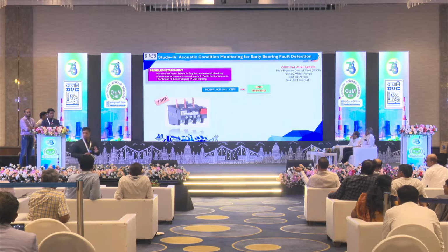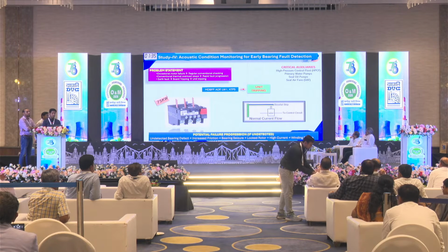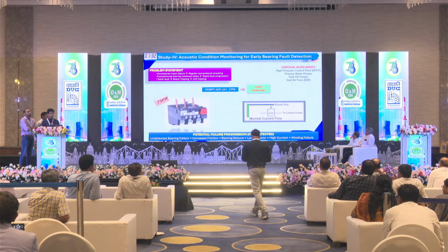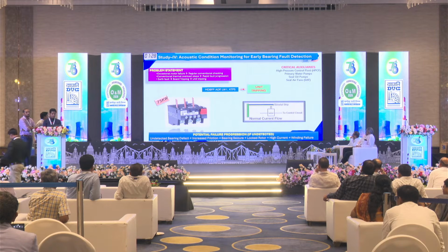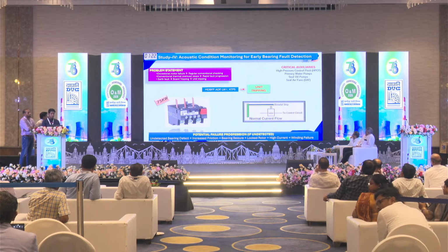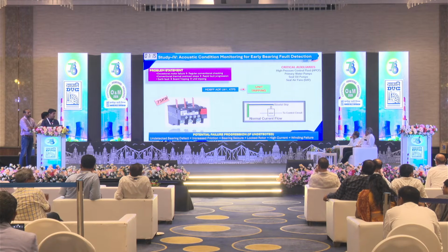Actually, drives up to 75 kilowatt are protected with thermal overload relay, and it works on the basis of thermal expansion of a bimetallic strip. So it needs certain time to operate. And this kind of undetected bearing fault leads to bearing seizure within a very short period of time. That creates a locked rotor condition, and due to that, winding failure took place, and earth fault also may be there. That leads to unit tripping. It was the case of MDBP AOP.